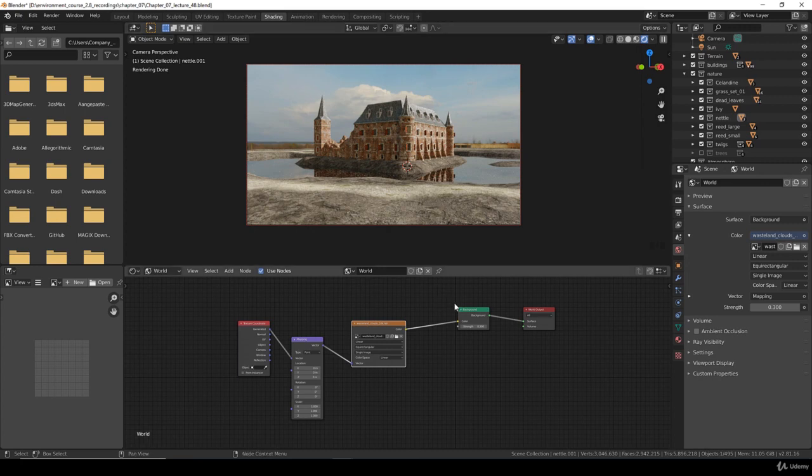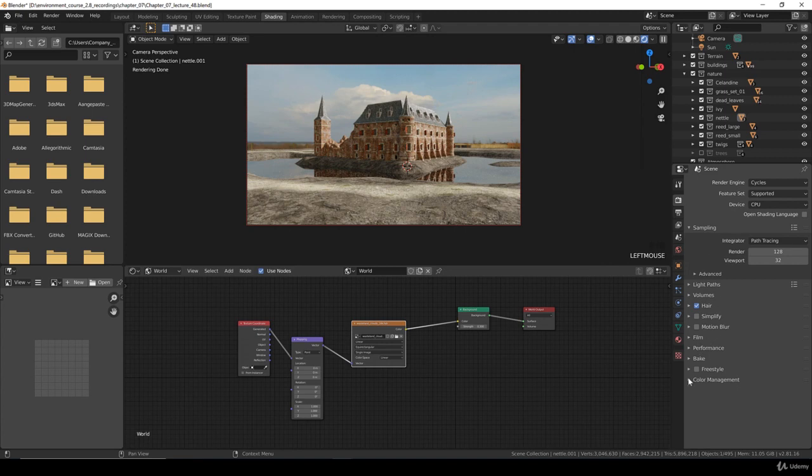That's much better. To improve this, go to your scene settings, go to color management, and change look from none to medium high contrast, and it will add more darkness. Just perfect. Don't go for high contrast because I think that's way too dark, but this medium high contrast, of course I tested this out and I was pretty happy with it.